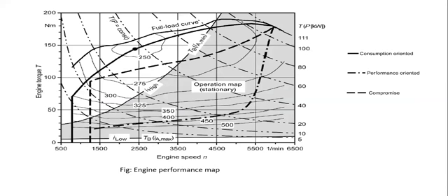So in this performance map, the information is found out by conducting a series of tests on the engine, and the program from these tests is called the engine mapping. These tests determine the performance and investigate the effects of each variable that has some bearing on the output of the engine. When the effects are known, the settings that give the best performance can be determined and recorded.